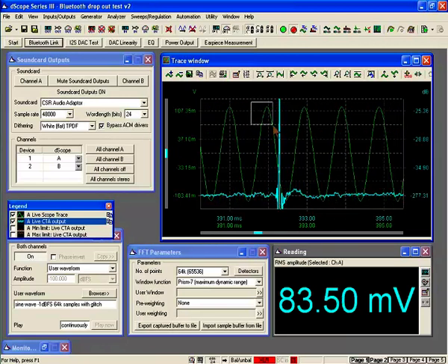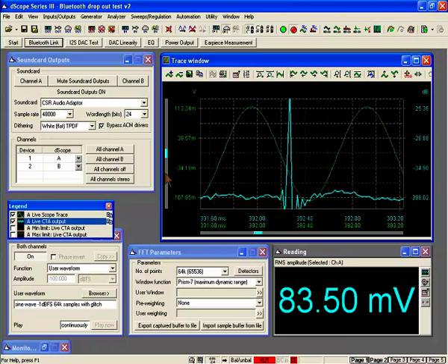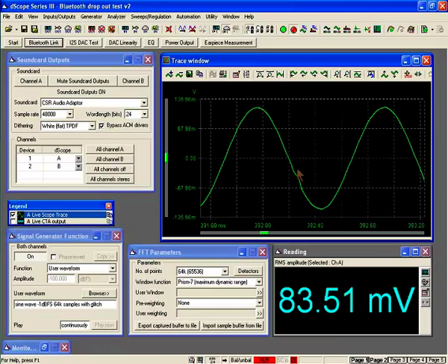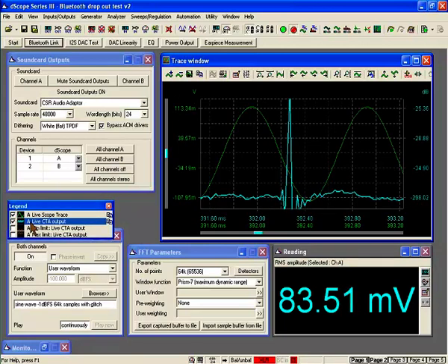zoom right in, we can see that even on this scale it's very hard to see anything wrong with the audio signal itself. If I just show you the sine wave here, what I have done is deliberately engineer a one sample deviation of 2 dB in this waveform that I'm playing out of the D-Scope system here over the Bluetooth radio link. And just this tiny little deviation in the waveform has been enough to cause a huge and measurable deviation in the peak THD plus noise residual.